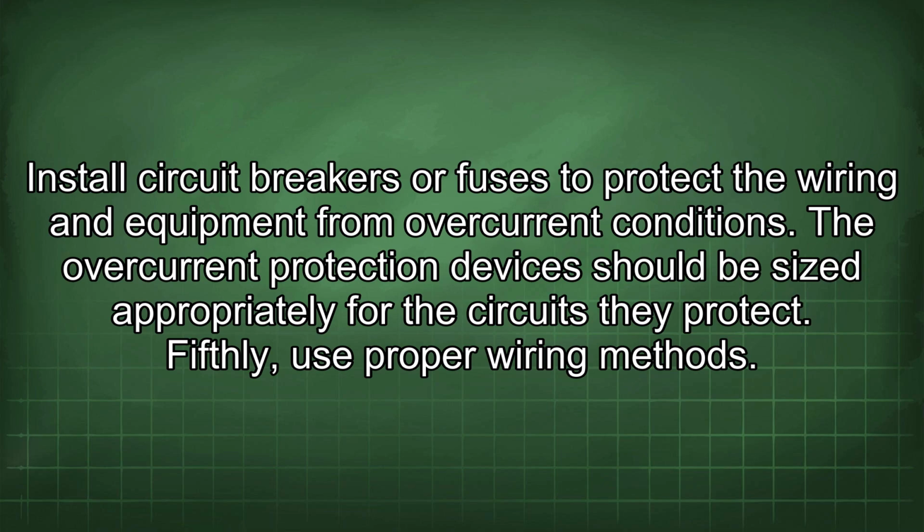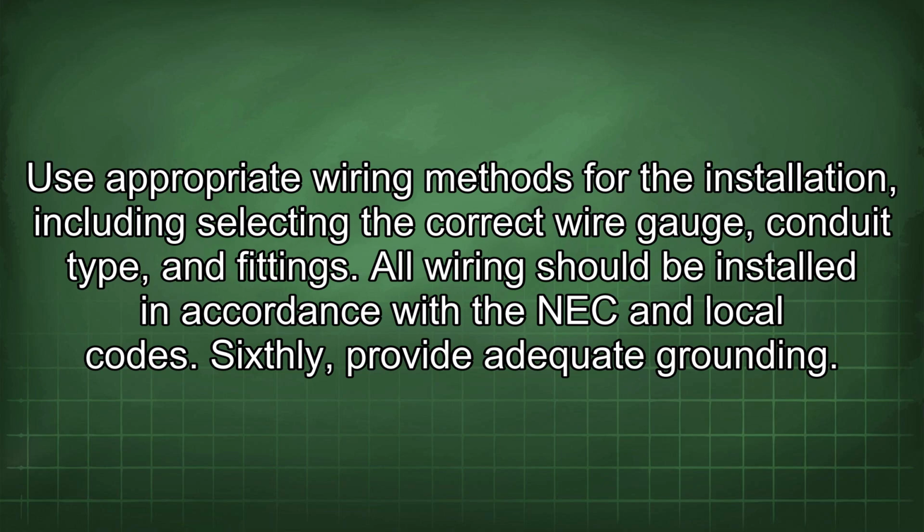Fifthly, use proper wiring methods. Use appropriate wiring methods for the installation, including selecting the correct wire gauge, conduit type, and fittings. All wiring should be installed in accordance with the NEC and local codes.